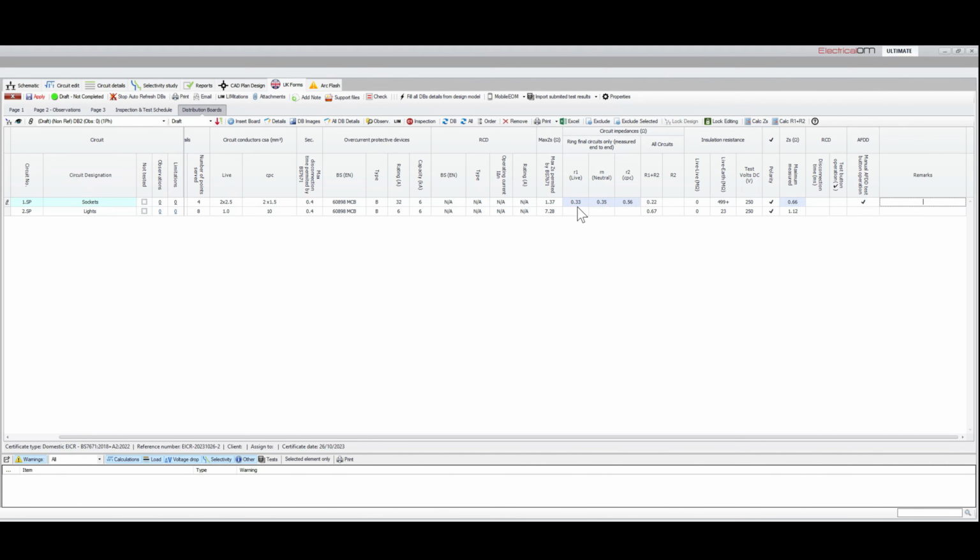I knew while I was recording these that the maths looked like it was playing out through the values I was seeing, but when you're not quite so experienced and just starting out on your testing journey, it's well worth checking as you go, because you might have put a probe in the wrong place or had something not connect correctly. You may just need to repeat the process and double check the values you're getting are actually accurate, and then try to find out the reason for them maybe not being as expected through the course of your inspection and test.